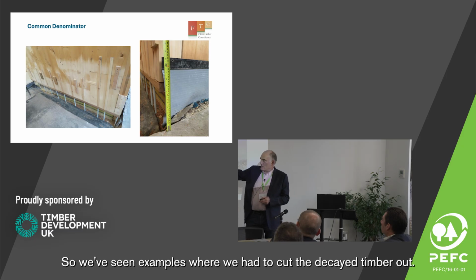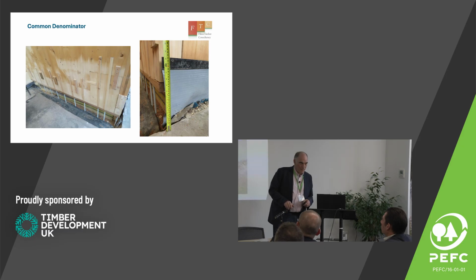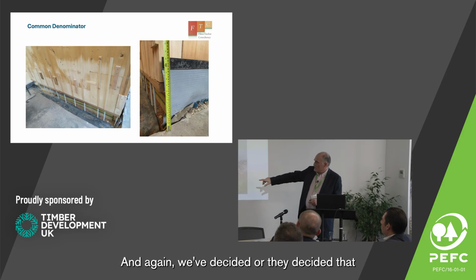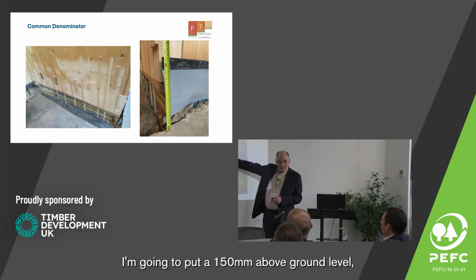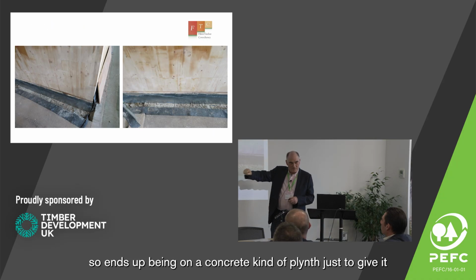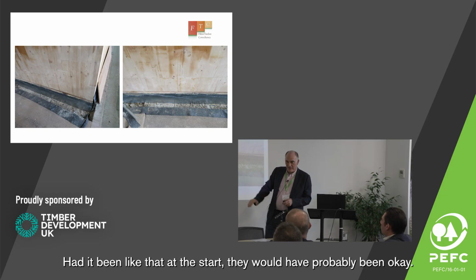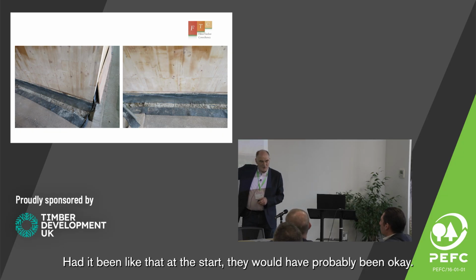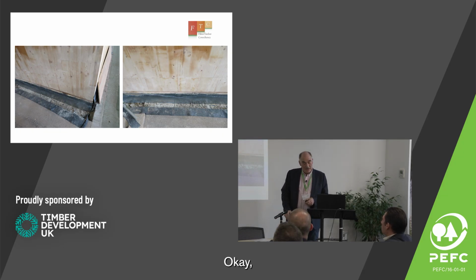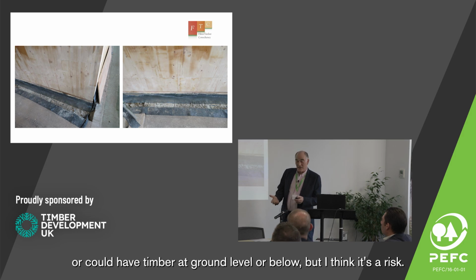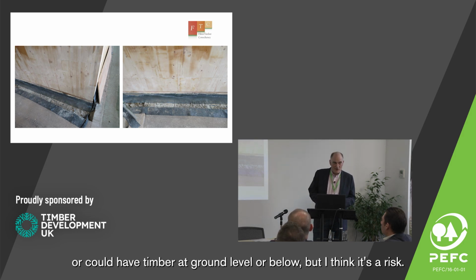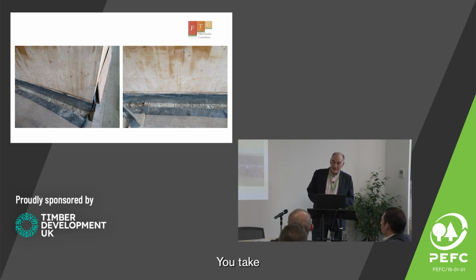We've seen examples where we had to cut decayed timber out, and they decided to put it 150mm above ground level, so it ends up on a concrete plinth. Had it been like that at the start, they would probably have been okay. People will argue that we should or could have timber at ground level or below, but I think it's a risk you decide to take.